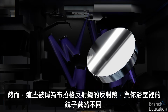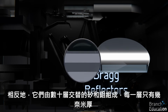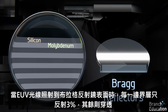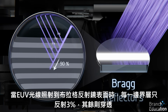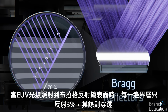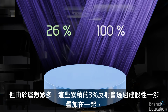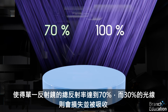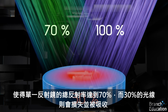However, these mirrors, called Bragg reflectors, are nothing like the mirrors in your bathroom, but rather they're composed of dozens of alternating layers of silicon and molybdenum, each only a few nanometers thick. When EUV light hits the surface of this Bragg reflector, only 3% is reflected at each boundary layer, while the rest passes through. But with so many layers, the cumulative 3% reflections add together using constructive interference, resulting in a total of 70% being reflected for a single mirror, while 30% of the light is lost and absorbed.